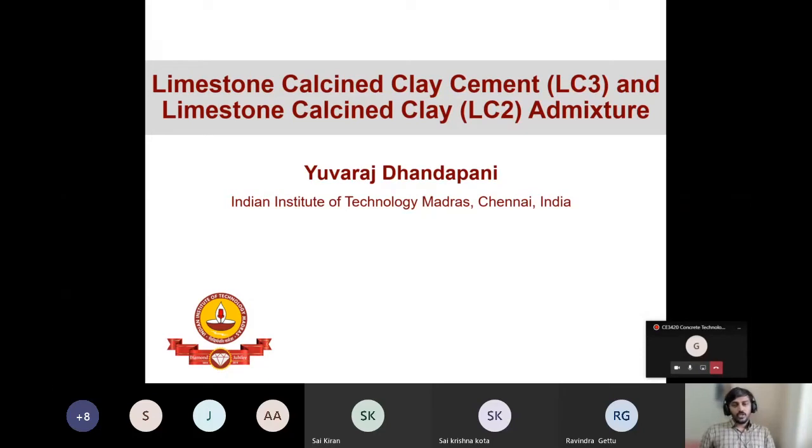So today I'll try to briefly give you some glimpse about limestone calcined clay cement, which is a new composite cementitious material which has been studied across the globe. And in line with the mineral admixtures lecture which we have been listening so far in the course, I'll also talk about how limestone and calcined clay as a combination can work as a very ideal mineral admixture.